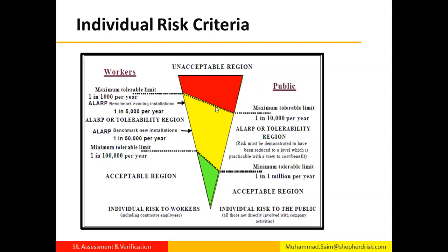Mission time could be the time period between 2 consecutive turnaround overhauls. Well, if you can afford to overhaul your ESD valves or your safety function every 2 consecutive turnarounds, well and good. But it's quite cost intensive if it involves big ESD valves or a number of ESD valves. If there are hundreds of ESD valves in a facility, you cannot overhaul all of them within 5 years or within 10 years. So you have to plan a longer mission time so that it is cost effective.